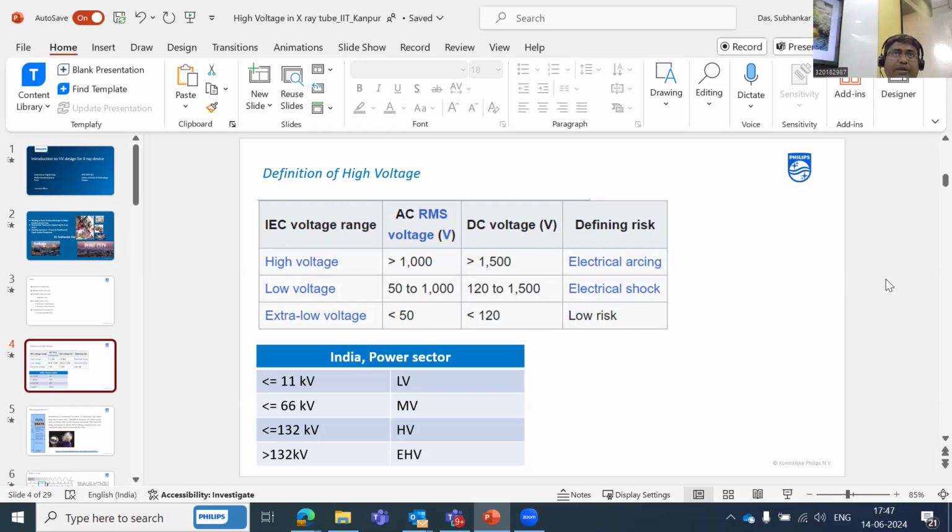The X-ray tube is a kind of replaceable component. Generally, high voltage instability is the major failure mode, and generally in 3 to 5 years, or 3 to 6 years maximum, it will be changed in a system. The entire system remains the same, with a new tube, and no oil filling or anything is done in the hospital or on site. It is only possible back home, at the factory. Any oil filling or oil top up is not done in the application area.